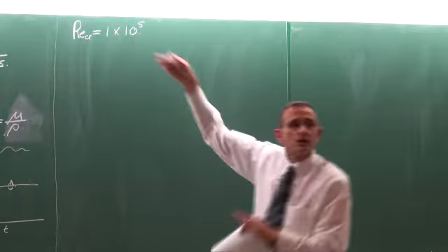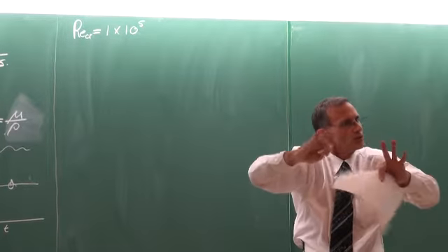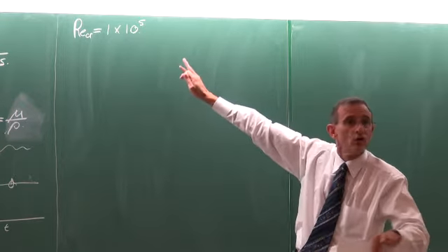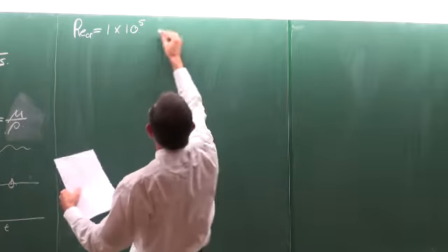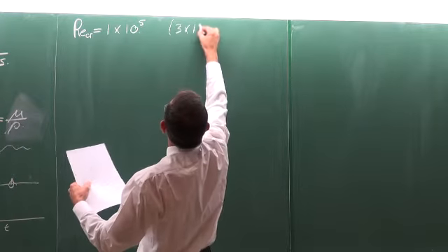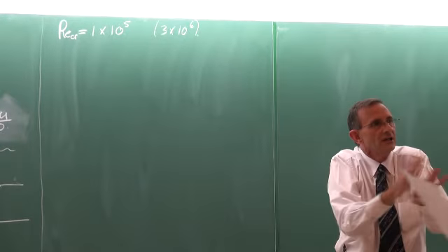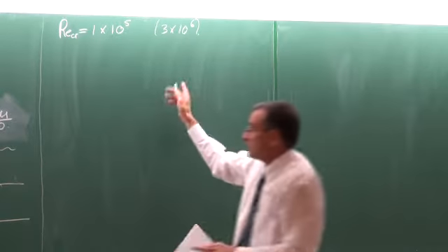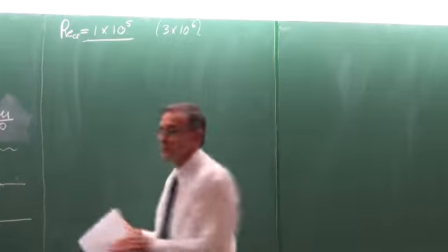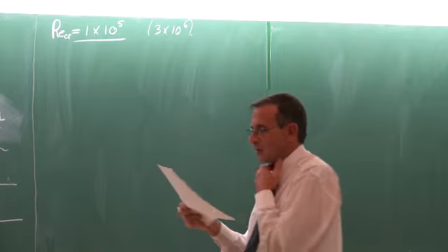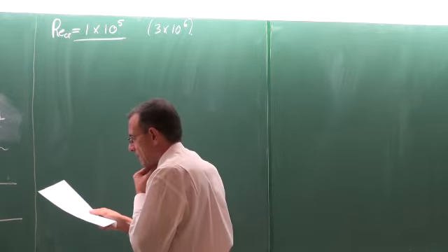Right, so the critical Reynolds number, our agreement in this module, is 100,000. It can be up to about 3 million and more in industry, so there's a gray area. But in this module, we're going to use 1 multiplied by 10 to the 5.